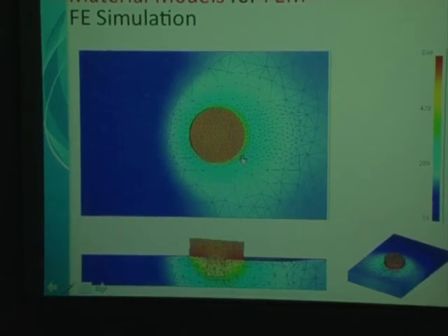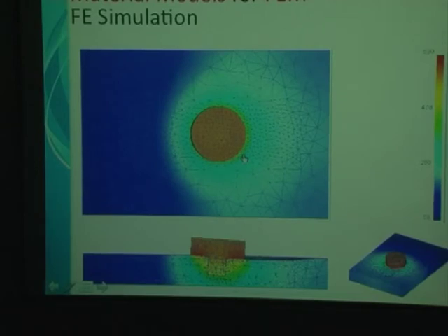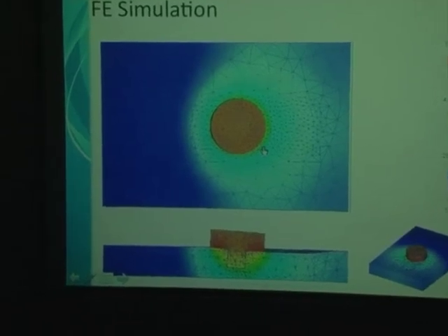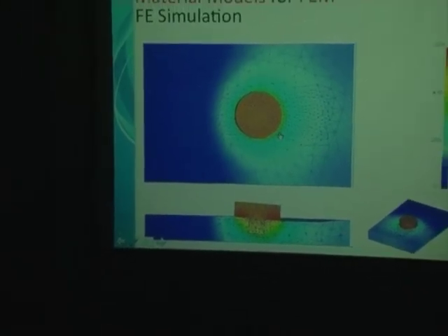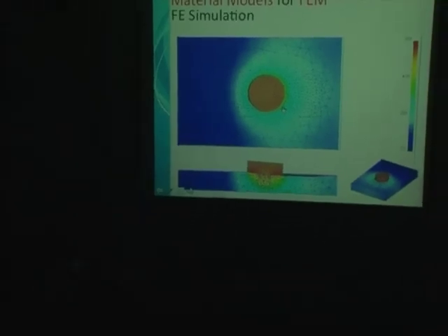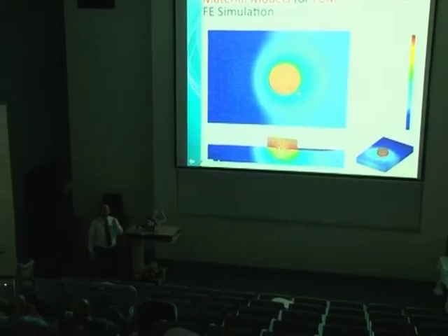Why is the tool pitched? The tool is not pitched. You know, if you don't appreciate the complexity of the process, it's very simple. There's about 20 different input variables. One of them is pitch angle. 3 degrees is known to be a good inclination angle. And again, many of those things have been vetted out over the years. For example, this is a very important factor. The other one is the offset in the direction of the advancing, another big factor. Pitching is really important. An important variable, yes, it is.